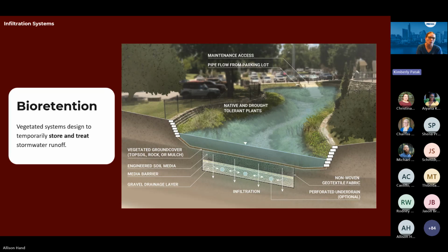And you'll want to have a multi-stage riser in your facility and allow the flood runoff to meet that still typical 24-hour drawdown, but the volume in the bottom that we're holding for the bioretention and the water quality improvements, you would want to hold for a longer period of time, typically 48 hours, but no greater than 72 hours, to make sure you're not creating a mosquito nuisance.